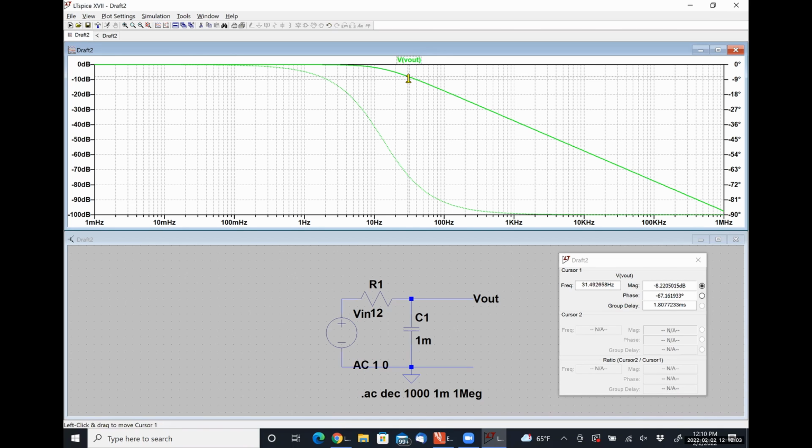Student: It's like a graph of how a practical filter dampens the voltage. Exactly right. So we can see that up until a frequency of somewhere between 1 and 2 hertz, literally all of the input signal is getting passed. At around this point, we start to see a small reduction. And as we increase in frequency, more and more of our signal is getting attenuated, right?